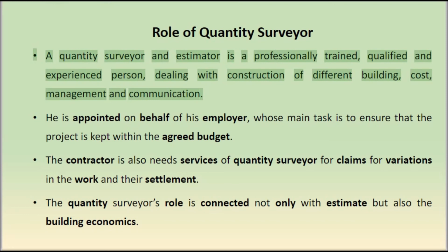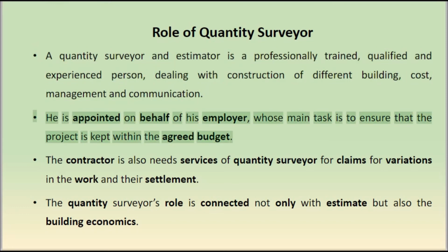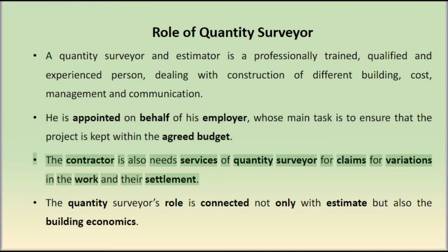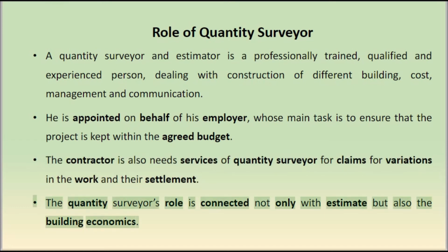He is appointed on behalf of his employer, whose main task is to ensure that the project is kept within the agreed budget. The contractor also needs the services of a quantity surveyor for claims for variations in the work and their settlement. The quantity surveyor's role is connected not only with estimates but also with building economics.